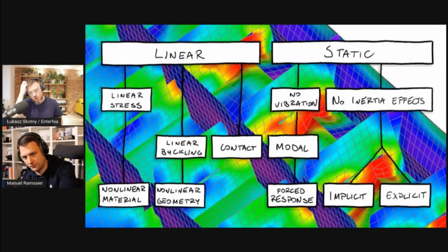And the drawback here is that you need to check for convergence and do all the iterations and stuff like that, which takes a lot of time. But the benefit is you as a user can actually define the time increment. So you could actually calculate a process that takes 1 hour to finish. Because in explicit, it only really works in situations where time is super, super quick. Yes, for small amounts, right? You can't define the time step.